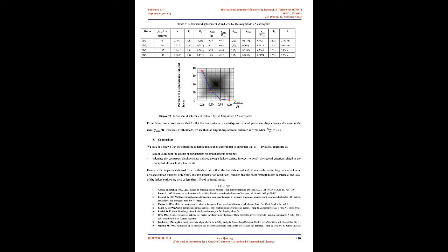Moving to figure 11, we find a damping coefficient equals 10%. The values of the spectral acceleration associated with the different modes are determined using the curve in figure 16, for damping equals 10%, multiplied by 1.6.